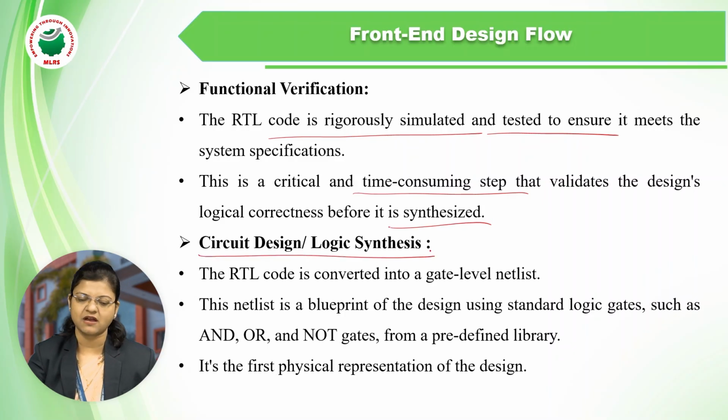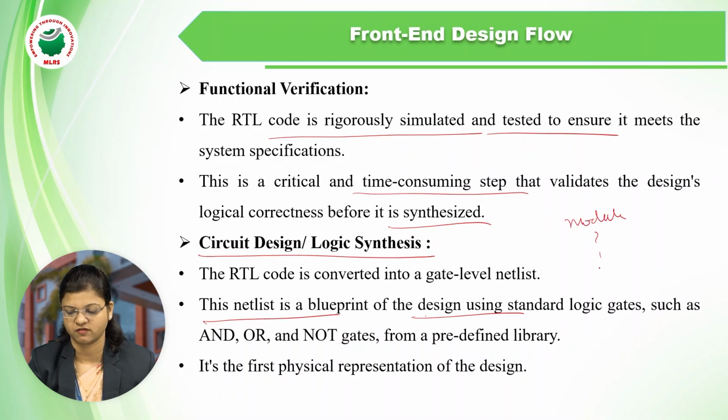After verification, we go for the circuit design and logic synthesis. There are different logic synthesis tools available in the market, which are used to create the gate level netlist. Whatever RTL code we have written is translated into the gate level netlist with the use of a logic synthesis tool. What is that netlist? Netlist is nothing but the blueprint of the design. Means whatever code we have written in the Verilog language or any VHDL.